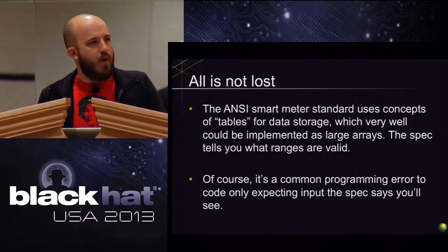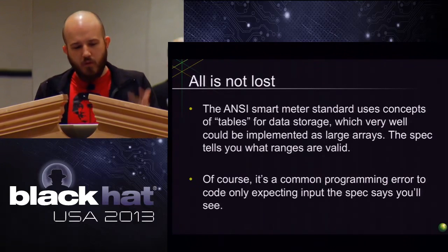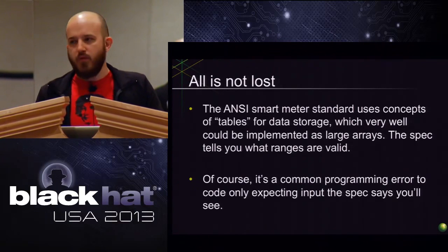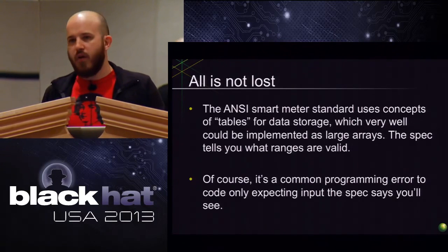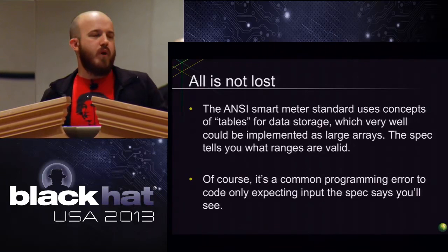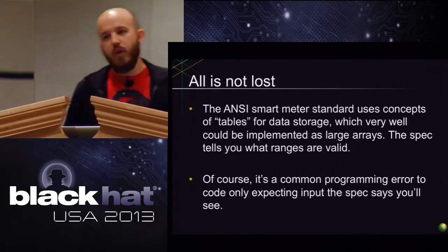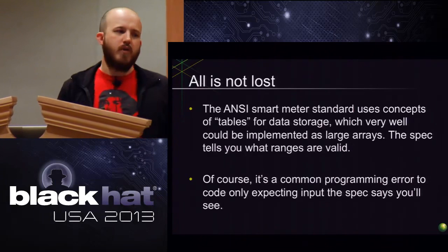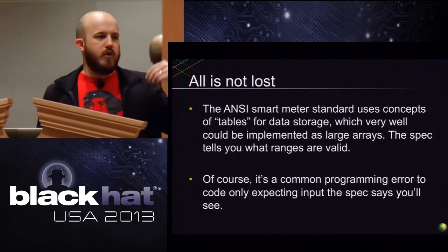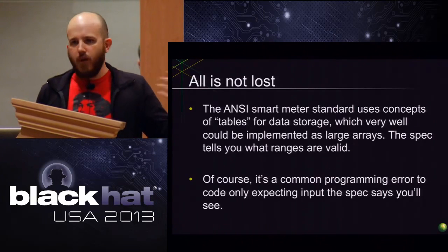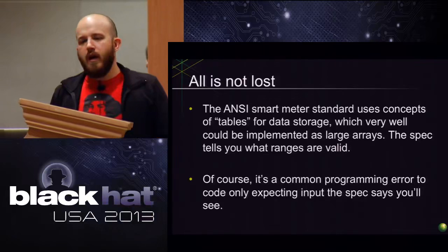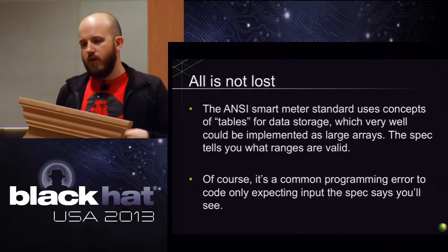But let's talk about the ways that you might be able to do this, and the ways that we'll demo here in a minute. So the ANSI Smart Meter Standard uses the concept of tables, right? If you saw Cutaway's talk, you know all about this stuff, or if you've seen one of the other ones. It's when you're reading memory out of data or reading memory off of a meter. Let's say you want to know how much power usage has been used over this period. Via the standard, you ask it the right way to say, hey, give me the contents of table 10, whatever. And then if you've got access rights to do that, it'll give it to you.